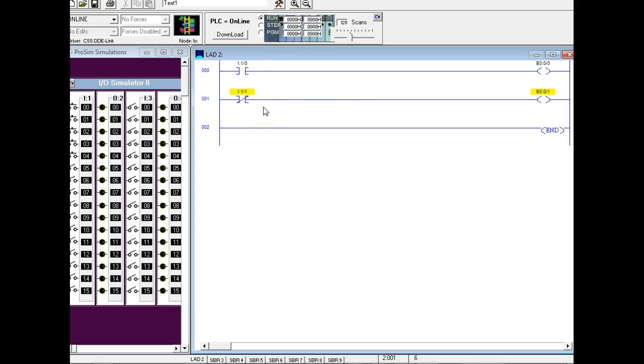Okay. But look what I'm using over here. So this is examine open. So what it says right now, it's open, so it's true. So it's open over there, so it's true. So it indicates the contact is closed because it's what? It's true. And this guy right here is entered that. But look what I had to use over there. Look at 1. What did I have to use? I used a normally open switch.